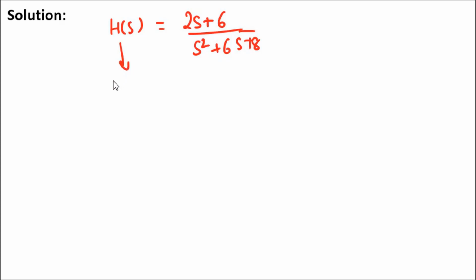Now coming to the solution, in this question you are given H(s) as (2s + 6)/(s² + 6s + 8). You can find h(t) from this H(s) by applying the inverse Laplace transform.